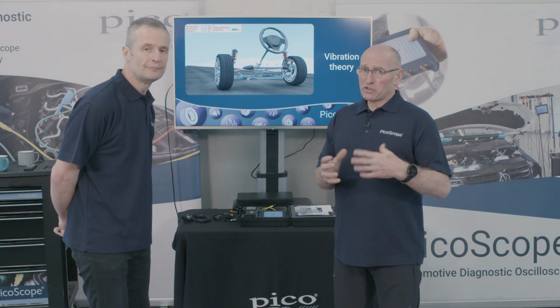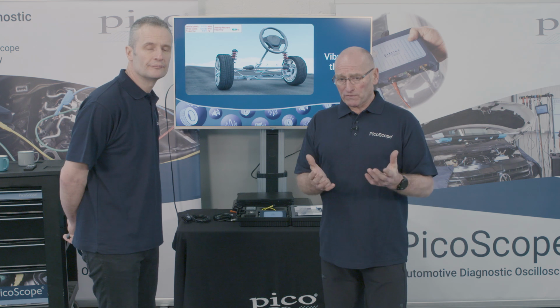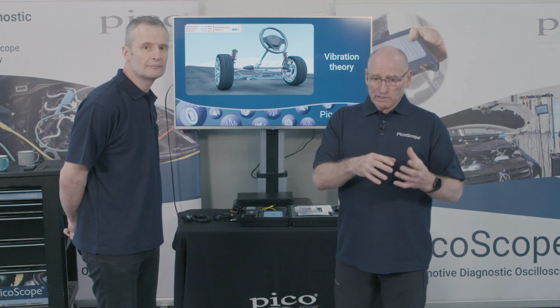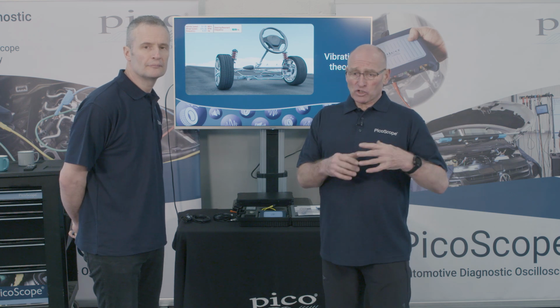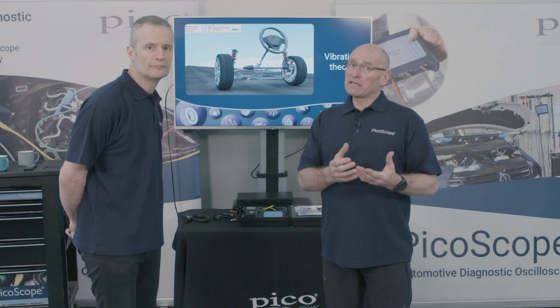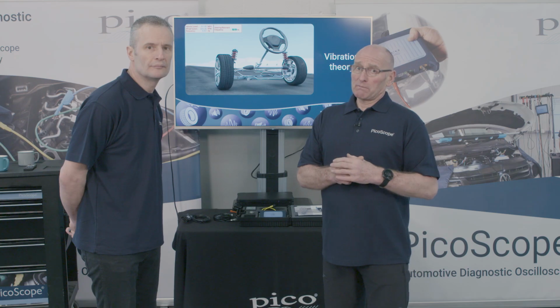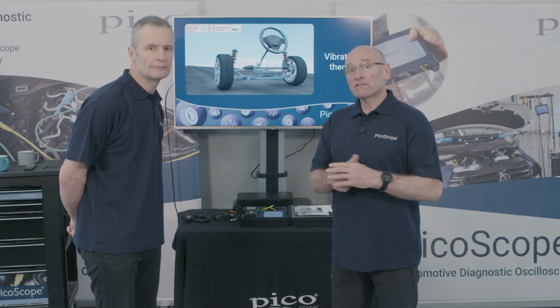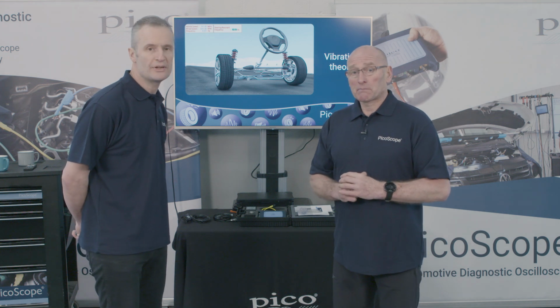I think the big issue here as a technician, from my point of view, is that in understanding the source, we're then actually preventing premature failure of components, because this energy has to be absorbed by different components: bearings, suspension, shock absorbers. If there is an issue there, it's important we deal with the cause of the problem, therefore protecting the life of a component from premature failure. Yeah, of consequential damage. Yes.